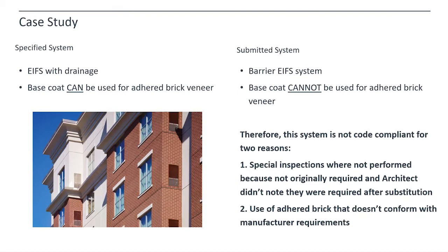Second, they also did not comply with the manufacturer requirements by using the thin brick veneer, because the code states that you must comply with the manufacturer requirements for an EIFS system. And so unsurprisingly, when we went to site, there were areas where the thin brick was detaching from the substrate.